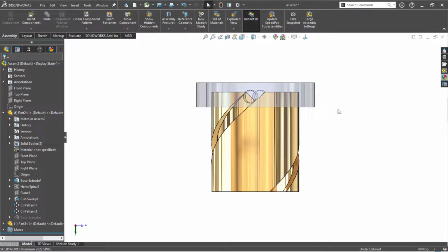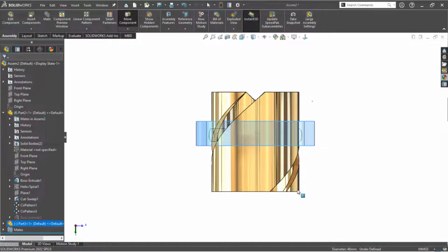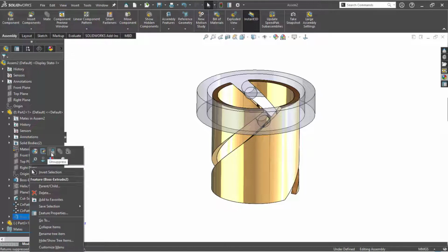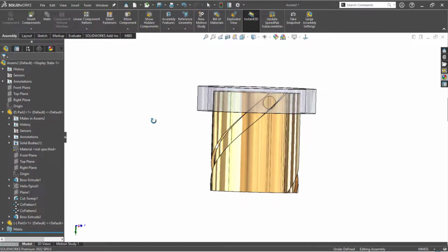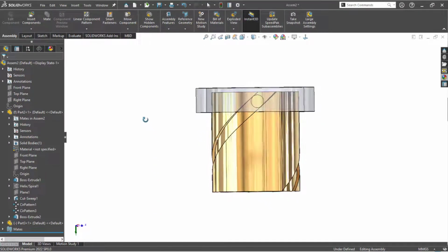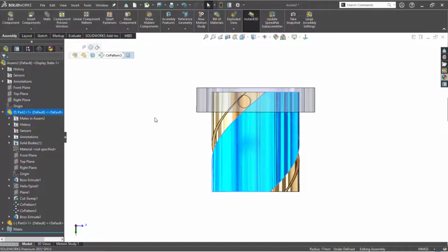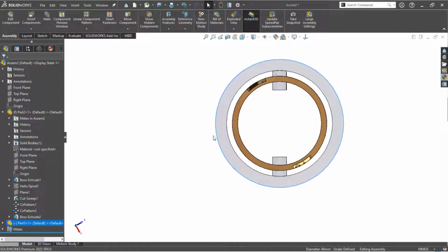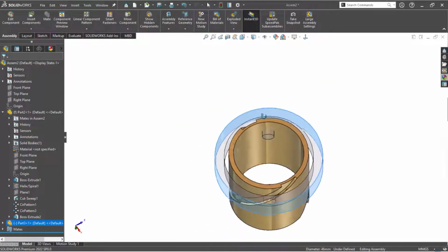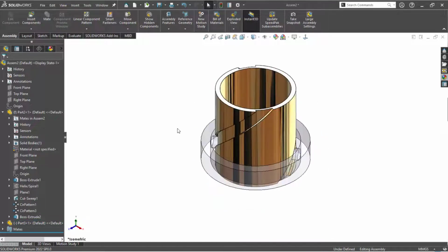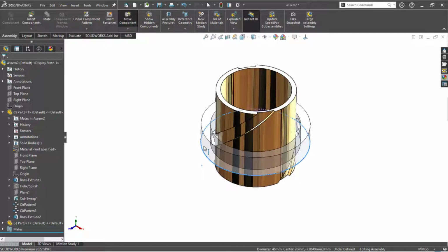Yeah. So one more thing, sometimes you might need only the grooves. You don't need exactly the cut section. At that time, you can use this one. You can simply draw the circle and close it. Some people find it difficult to create this kind of structure. Simply use the top face and draw the sketches, circles, depending upon your requirement, and you can easily have this kind of mechanism. This top portion you can do however you want. See, this is a circle, two circles, simply draw it like this. So this is how you can deal with these kinds of advanced mechanism portions if you want to create them.